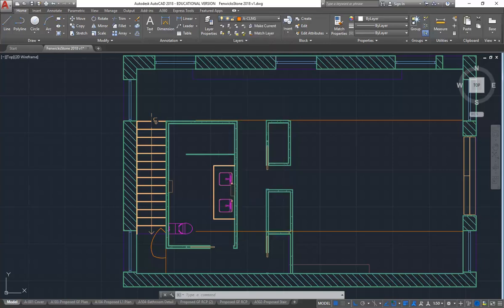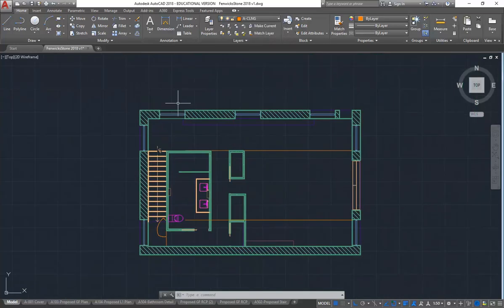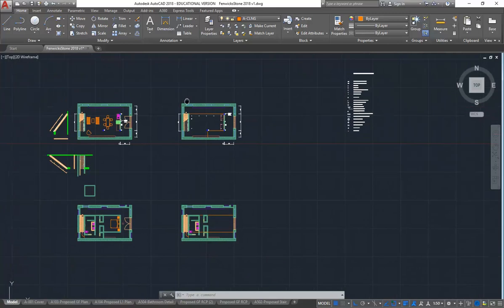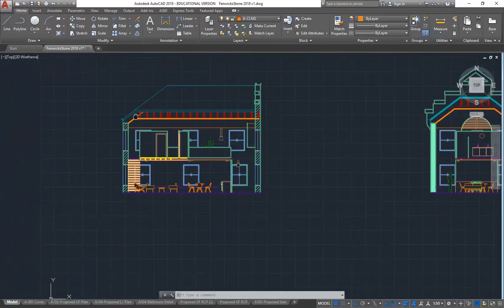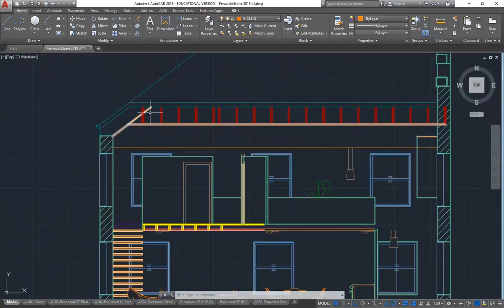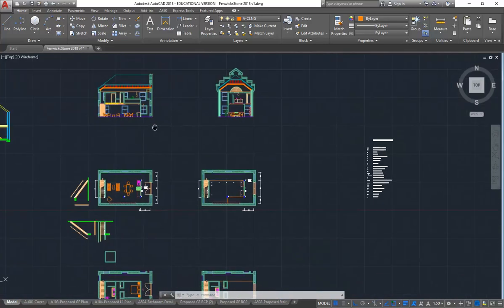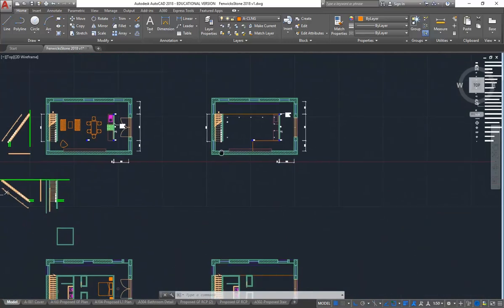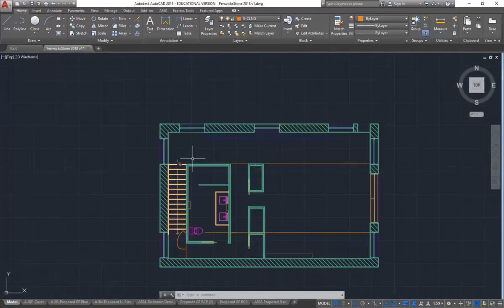So again, if you're lining that ceiling, you're going to see the angle here coming up. And it might seem like a tricky thing to work out, but it's actually fairly easy because we know that any two roof shapes that join together of the same slope, if they're at the same angle, they'll join together at 45 degrees.